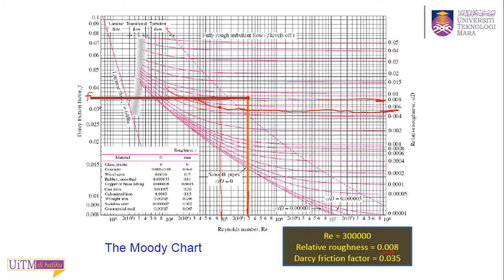Faham sir. Okay, so you cannot just simply draw a straight line. You need to draw your line as a curve after you reach this dotted line. Because this is the turbulence region, that's why the Moody chart draws something like that. So you need to draw a curved line. Maybe there's a small error because your line is not exactly curved, but that's fine. That error will be very minimal. So that's why we still use the Moody chart.